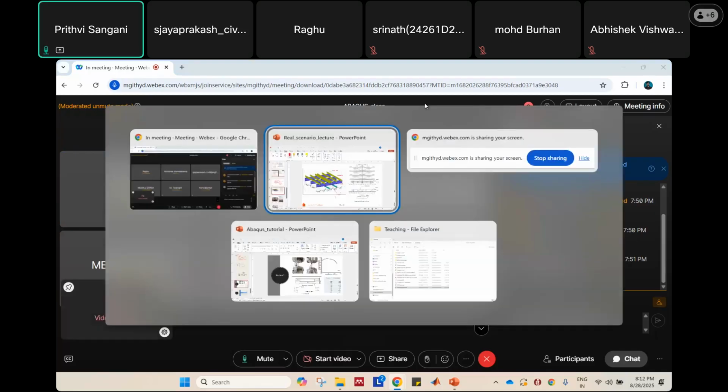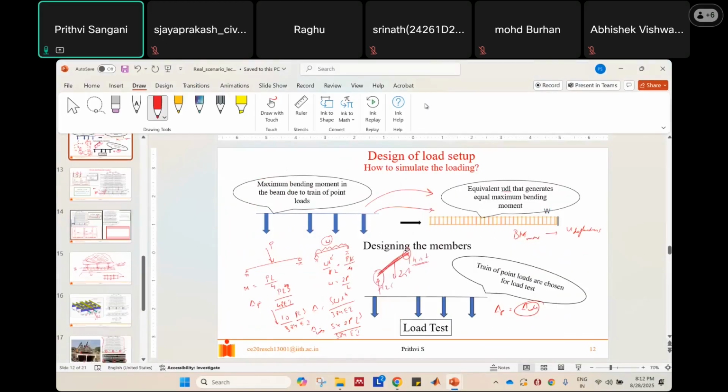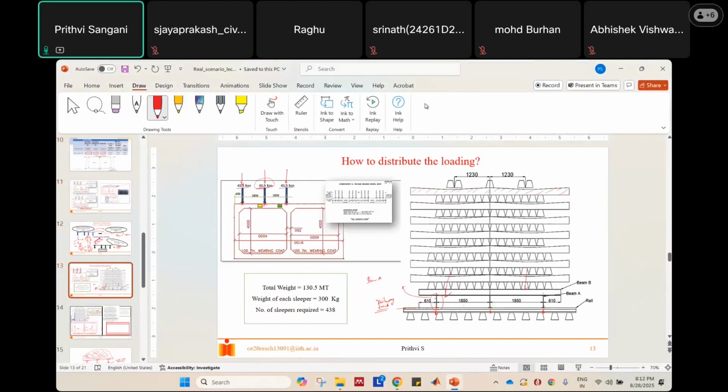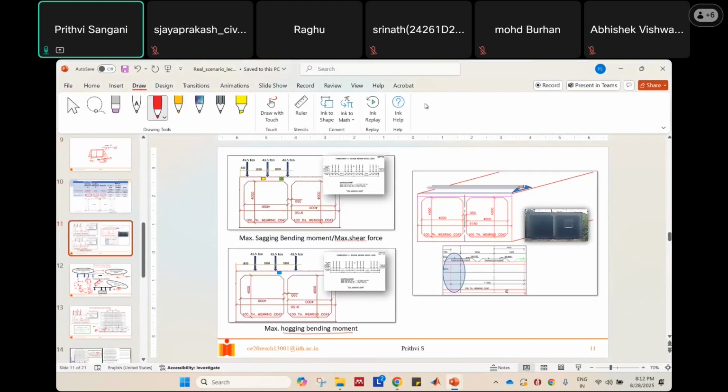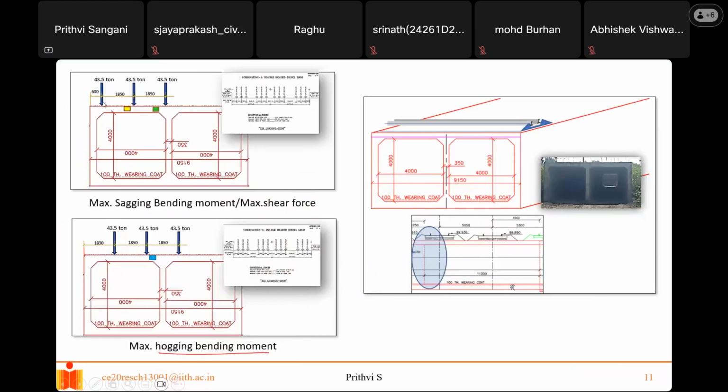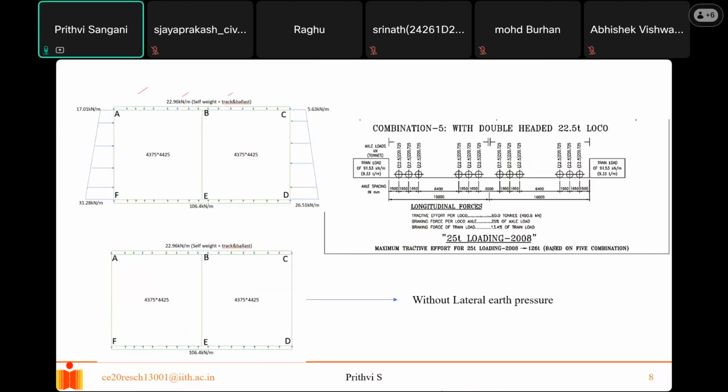Yeah, that's actually a very good observation. If you remember, this 43.5 was without the surcharge included. But when the wheel loads are placed in this configuration, that was with the surcharge load. We have placed some surcharge on top of the beam, because that's how we asked them to create the entire surcharge. Whatever we are going to see in future, like an embankment with compacted soil, on top of it ballast, and on top of it the track, was replicated in the testing as well.